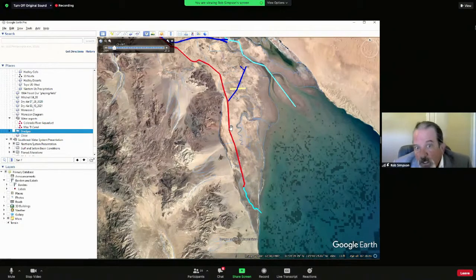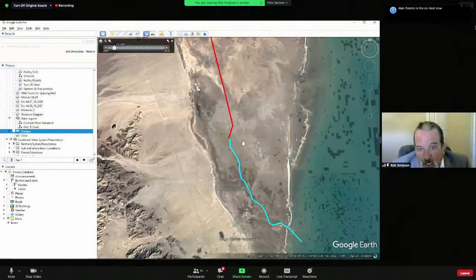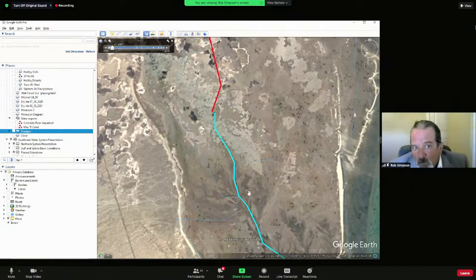Within those 6 days, we could dredge what's called a pilot channel, 2 meters deep, 3 meters wide, from here all the way down to there. We'd stack the dirt up on this side. This concentration of flows would induce great back cutting down here. I don't know if you guys have ever seen this. These little branch-like structures right here are created from water flowing up onto the floodplain and then back cutting, just like Niagara Falls back cuts.